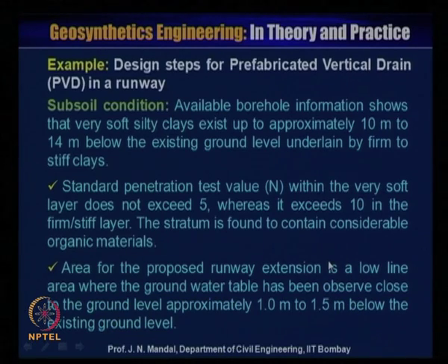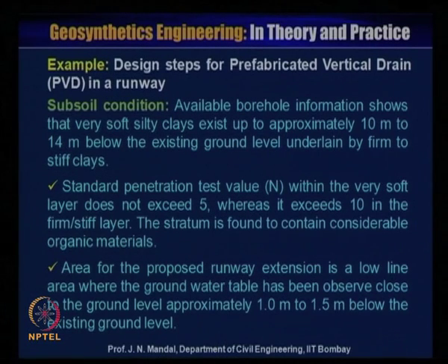Here one example is given, the design steps for prefabricated vertical drain PVD in a runway. So this is one of the projects. The subsoil condition: available borehole information shows that very soft silty clay exists up to approximately 10 meter to 14 meter below the existing ground level, underlain by firm to stiff clay.